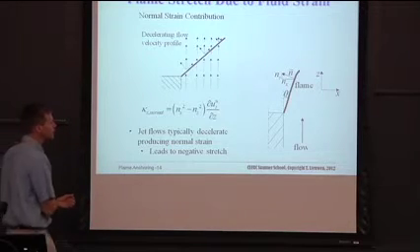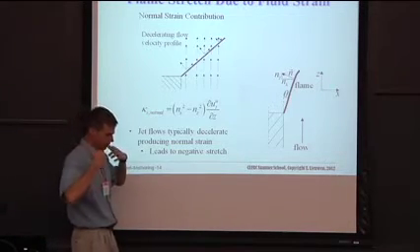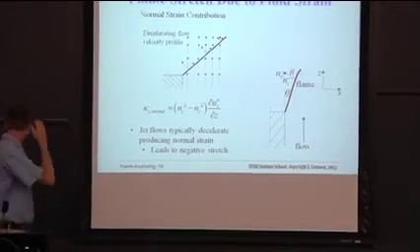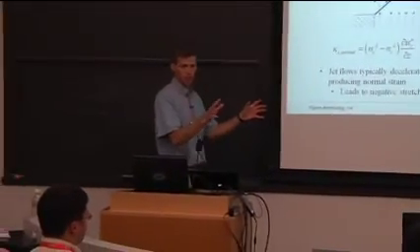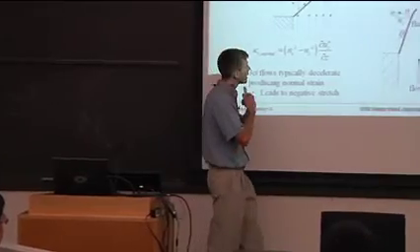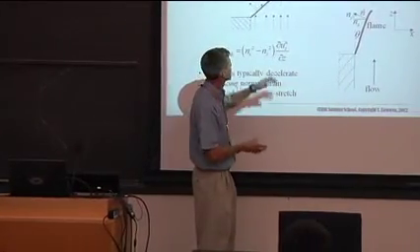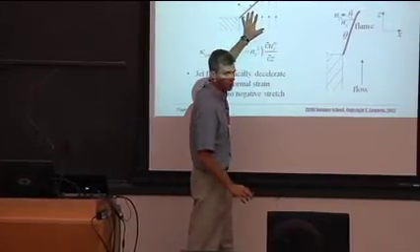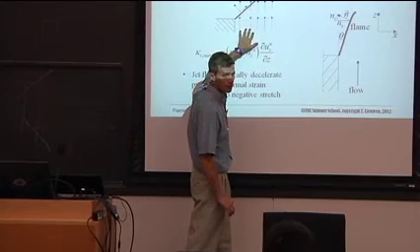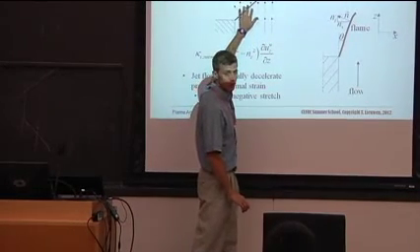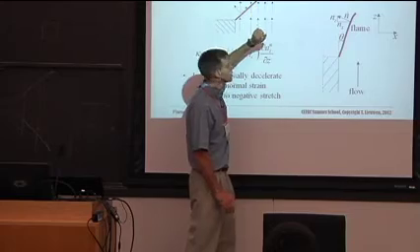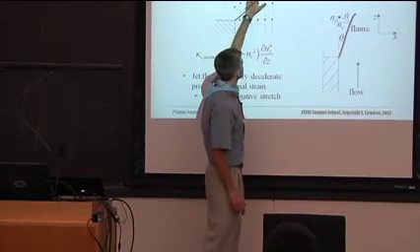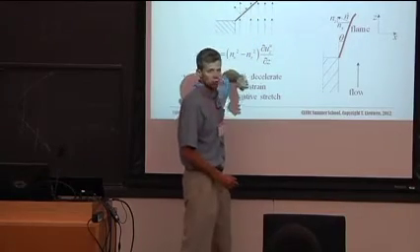Generally in combustion chambers, the flow accelerates abruptly when it goes into the combustion chamber because there's a rapid expansion. So I'm going to assume that as the flow exits into my combustion chamber, it's decelerating. I'm going to ignore the shear part for a minute, but I'm drawing my velocity vectors. I've got high flow velocity here, and then it's decelerating as it's moving up. Okay? So this is causing fluid mechanic strain.